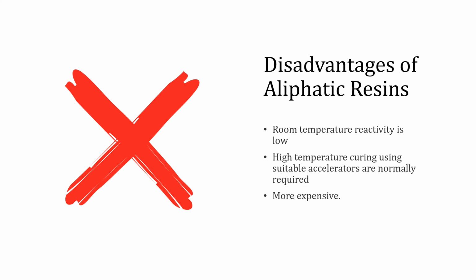Therefore, sometimes there is no need to use these types of epoxy resins. In fact, the economy of the project and the required properties dictate whether these types of resin can be used. For a flooring project in which the outstanding properties of cycloaliphatic epoxies are not required, the employment of these types of resin just imposes a cost. As a rule of thumb, when substituting a bisphenol A-based epoxy resin with a cycloaliphatic, the costs are increased by 20% to 25%.